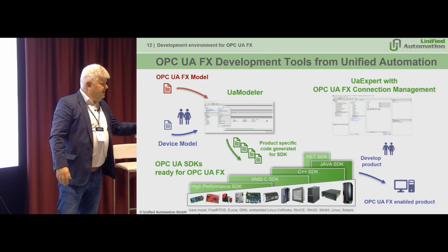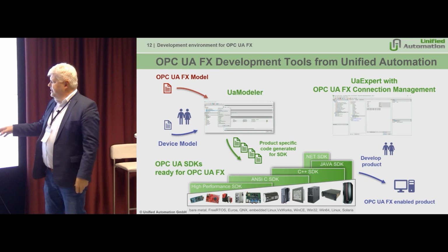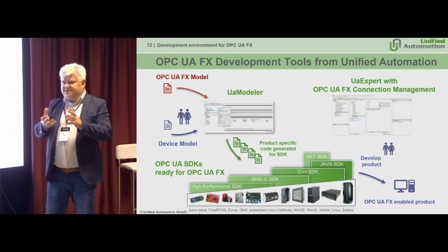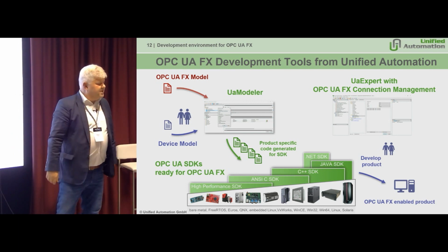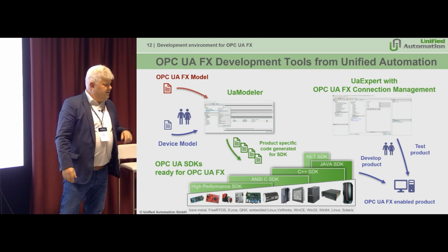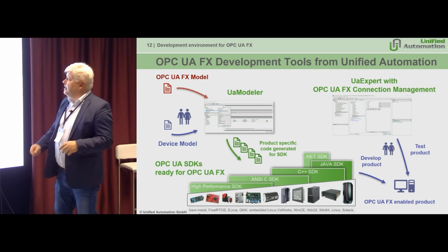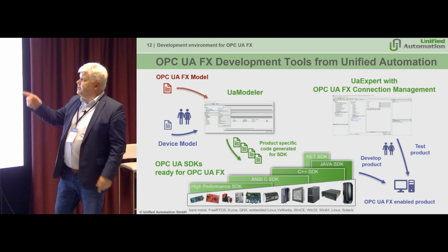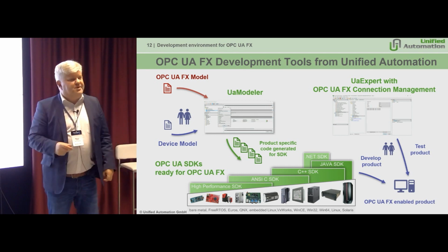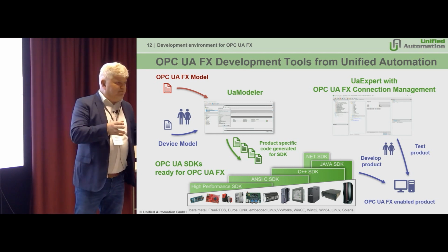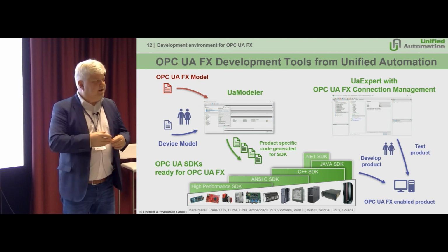And then you create a first FX automation component, and then we have an OPC UA FX connection manager implementation in our UA Expert. So we already have a PubSub configuration capability there.